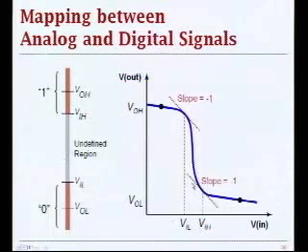They correspond to the 45-degree slope on the voltage transfer characteristic over here. So you have nominal values, and you also have VIL and VIH. VIL, the input low voltage, is the maximum voltage at the input that will still be propagated to the output of a gate and be treated as a valid logic level.